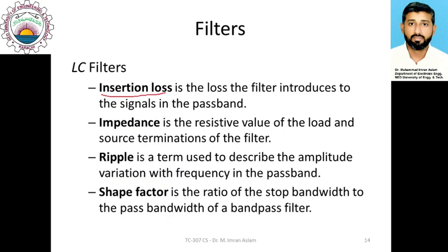Insertion loss: as we know, all circuits, whenever they are used in any system, exhibit some loss in the system. Similarly, each filter, whenever it's incorporated in a system, also provides certain loss whenever a signal passes through that particular filter. So the loss when the signal passes through the filter is named the insertion loss.